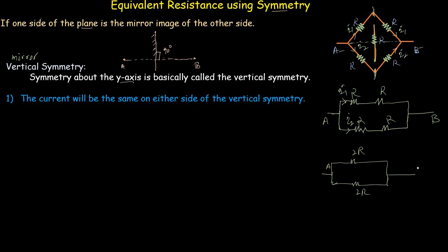This is point A and this is point B. Now the equivalent resistance of these two branches will be 1 divided by R equivalent equals 1 divided by 2R plus 1 divided by 2R, because these two branches are sharing the same 2 points, so they are in parallel. After calculating this, you will get R equivalent equals R.